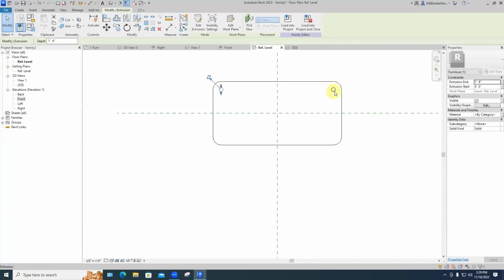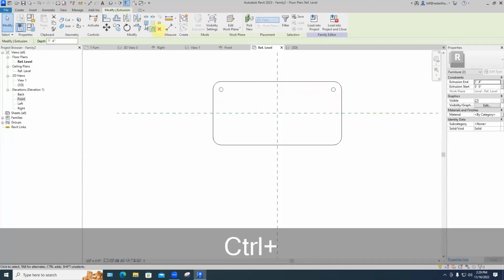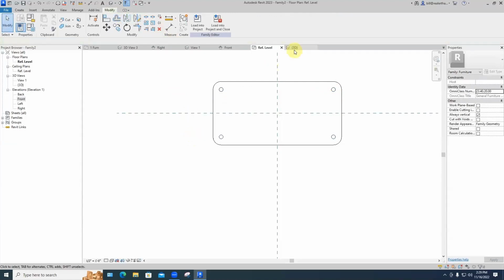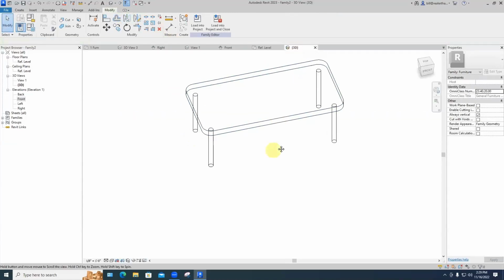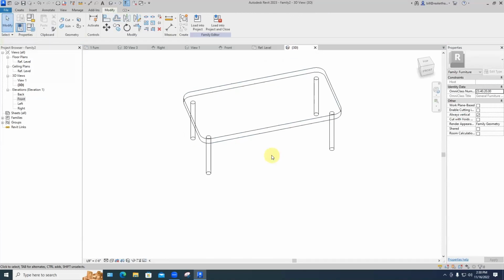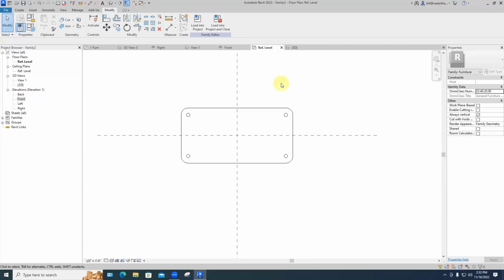Click the first one, control click the second, mirror, pick. Control sort of has a copy function. When you control drag, it'll make a copy of something, and control click, it'll keep picking up pieces as it goes. So that sort of two-stage mirroring is really common for lots of furniture pieces that you'll be working on.